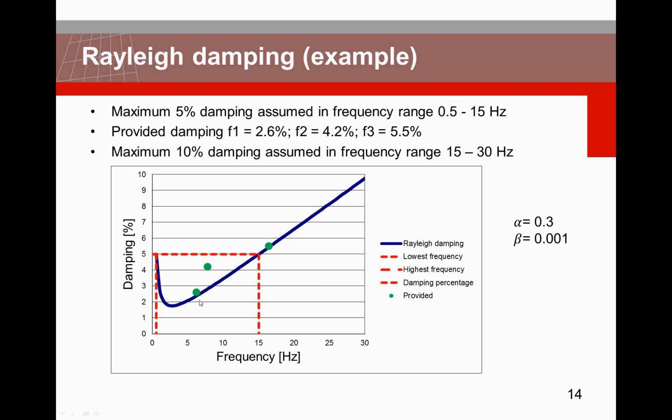So don't focus only on just 2 frequencies, but think about the entire range. What do you expect for your response? What is the frequency in your loading? And take all these things together while setting up the Rayleigh damping properties.